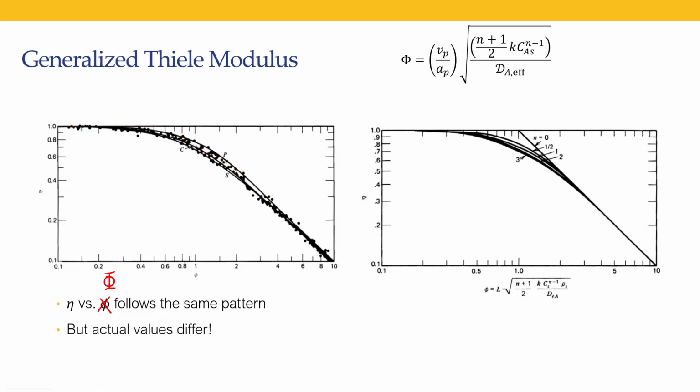Okay, two things to note, and once we do the derivation we'll come to that in tomorrow's lecture. One is the asymptote at low Thiele modulus, and the other is the asymptote at high Thiele modulus. Where phi, let's talk about slab or anything else.